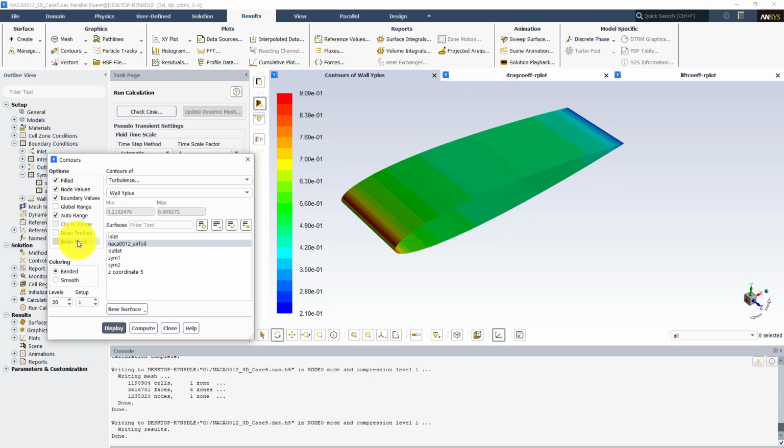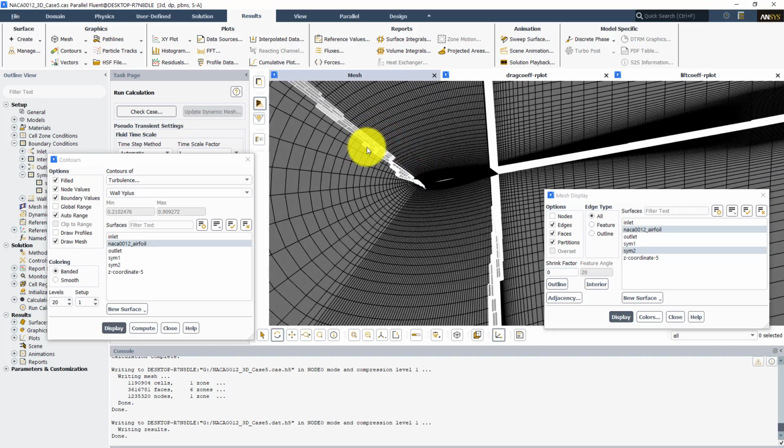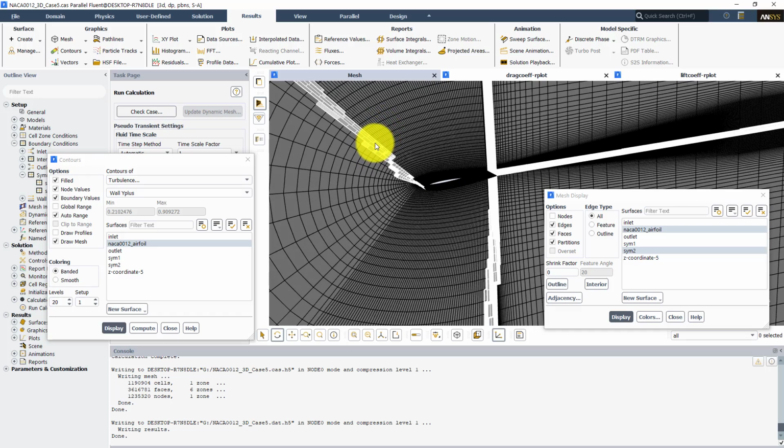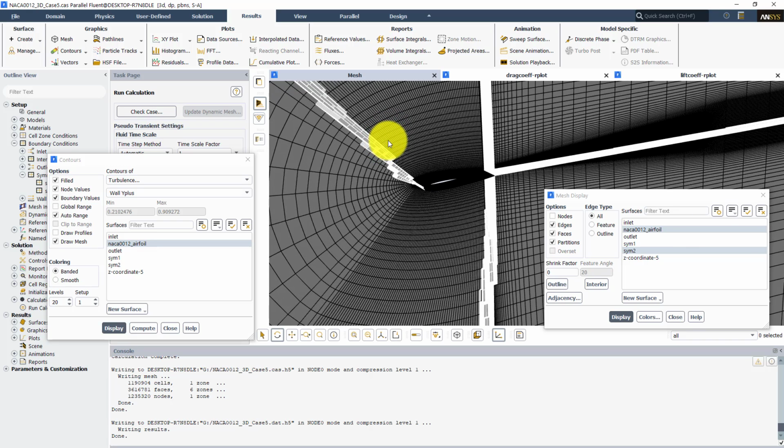So it means that the problem was not inside Fluent 2020 release 2 or in the parallel solver or in the pressure based coupled solver, but the problem was in the automatic partitioning done by that version of Fluent. So at the moment I guess that you should manually partition your grid by yourself whenever we have a very fine mesh. This happens sometimes. For a larger boundary layer region, I didn't see this problem happening here. So this might be happening in some few cases, and hopefully they solve the problem for these typical cases.